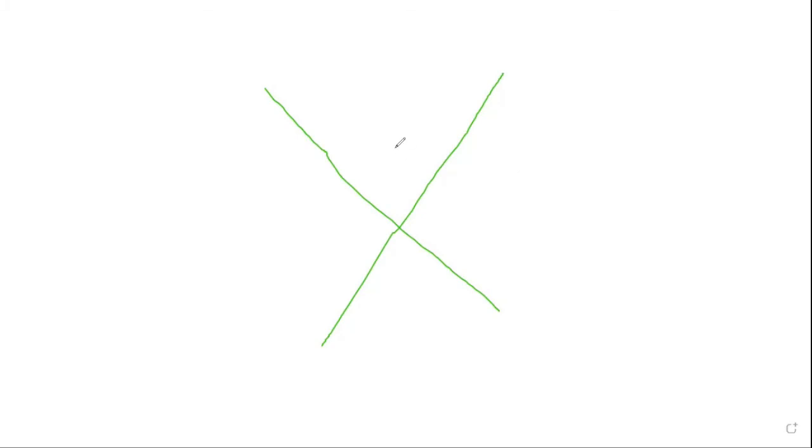These conjugate shear fractures are really good tools, structures to estimate direction of sigma 1, because sigma 1 will be the bisector of this narrow angle. And in most cases, that will be a 30-degree angle between sigma 1 and fracture plane.